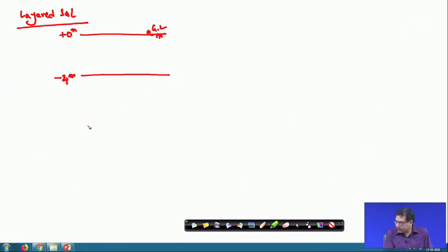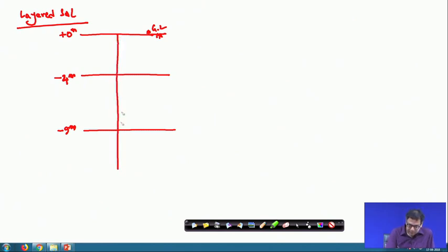Then the second layer is 5 meter, that means up to minus 9 meter, and then the pile is inserted here. So, the total length of the pile is 14 meter. The pile base is at minus 14 meter. So, this is 4 meter plus 5 meter plus 5 meter, which is 14 meter.